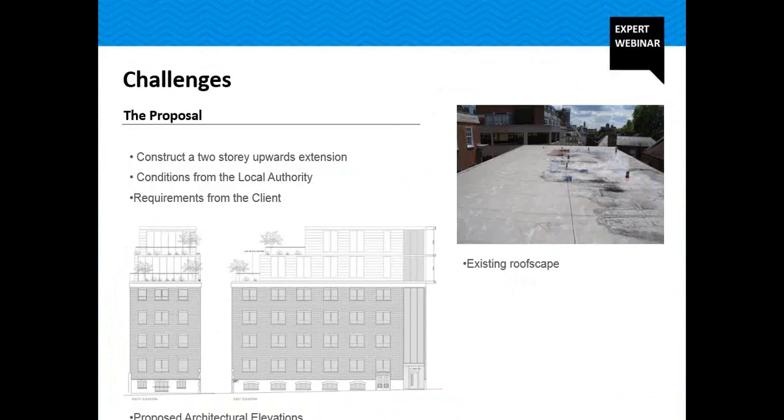In order to obtain planning permission from the local authority, we had to work with the condition that the proposed extension would not affect the rights of light for the neighbouring buildings. An independent survey produced results which required each additional level to be offset from the facade of the floor below, and also put a height restriction on the proposed development. The finished floor-to-ceiling heights affect the perceived comfort of space, and this impacts the sell-on value. Here you can see the proposed architectural elevations.